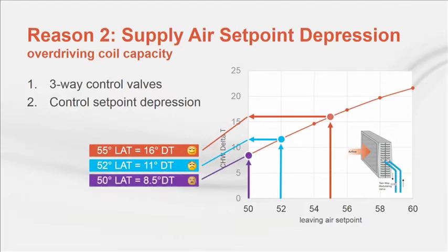Tomorrow's result? A full load delta T of 8.5 degrees, requiring almost double the design flow, if the pumps can produce it, and close to 8 times the system pumping energy. Based on my experience and case studies I've read, this is the #1 ongoing cause of excessive low delta T. Coil control set point discipline is critical in the maintenance of system delta T.